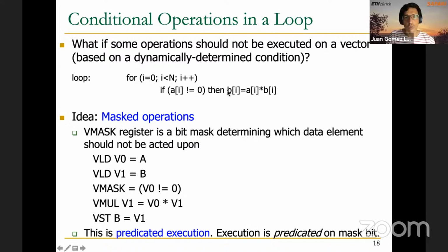Is there a way to overlap the vector loading with only one port? If we have a single port per memory bank, we can only have one single load or one single store per memory bank. So we are exploiting some parallelism by using multiple banks. In some systems, we may have multiple load ports and multiple write ports as well, so on the same bank we can be reading or writing at the same time. But if we have a single port per bank, I don't think that we can perform two loads from the same bank. Thank you, Bekhtat.